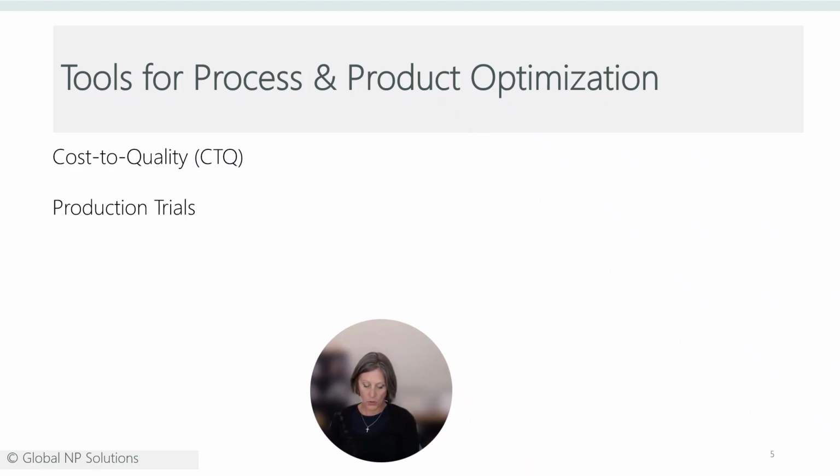Our client that sold household appliances used 2 manufacturing scale trials before releasing new products to commercialization. The first test was to verify that tooling and equipment could manufacture the appliances to specification, producing less than 100 devices. An adjustment period followed to make corrections to factory equipment, packaging lines, and product handling. The second production trial then validated throughput and quality for a few thousand devices.